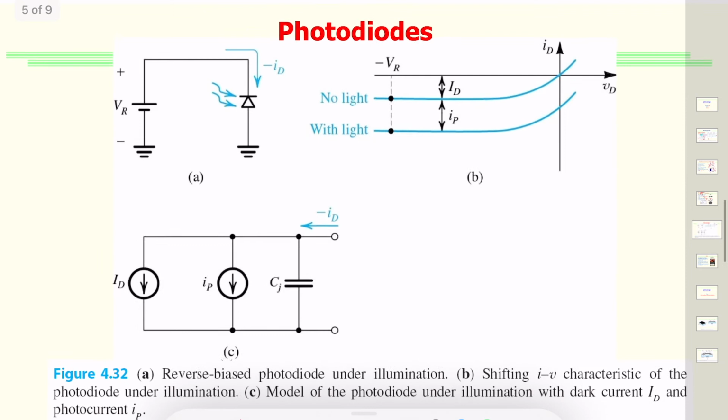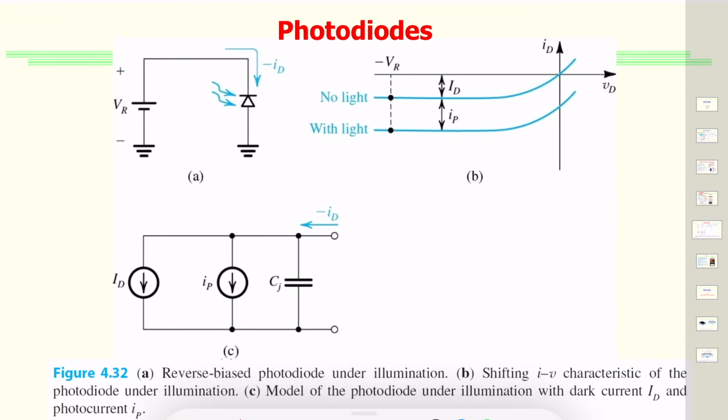Another very interesting and very important application is what we call photodiodes. If you think about a diode in reverse bias, there's no conductivity, right? Now, if a reverse bias PN junction is illuminated, we throw light, and these are specific wavelengths we'll talk about, but let's generalize this. We illuminate it with photons. The photons that impact the junction cause covalent bonds to break, which means they would create electron and hole pairs in the semiconductor material. And that would result in many more electrons and holes becoming available in the depletion layer.